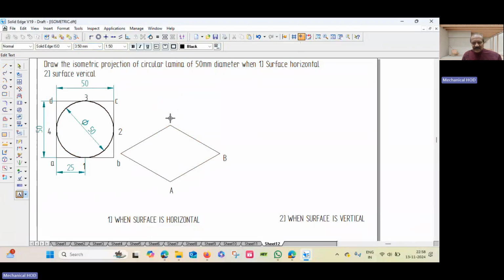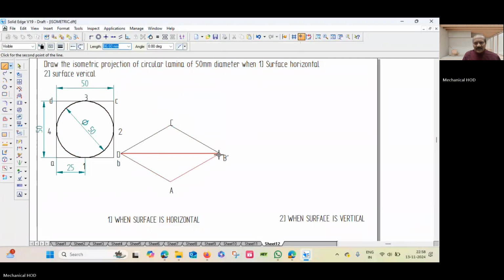So this is ABCD as we already discussed. Then join the bigger diagonal. Here the bigger diagonal is DB. Then from A, draw a line to the center of DC. When you scroll on this, you'll get the midpoint symbol. When you get it, click. Similarly, start from A, scroll on BC, you get the midpoint symbol, click it.